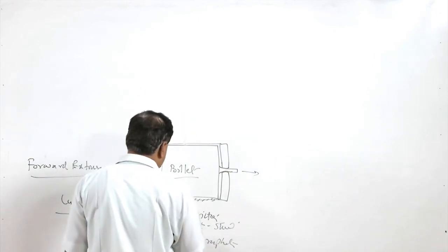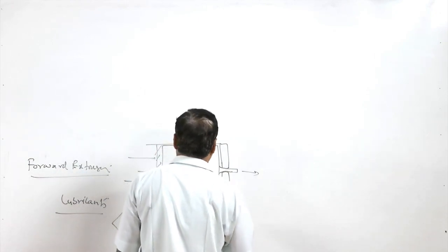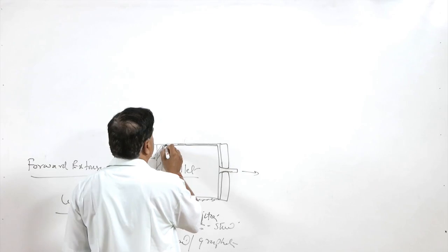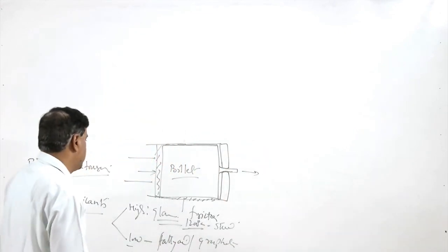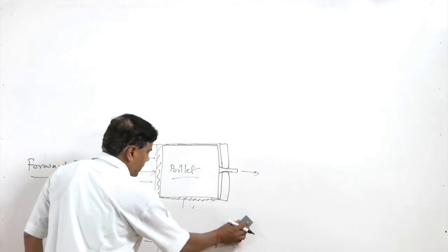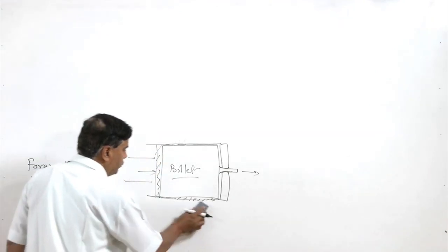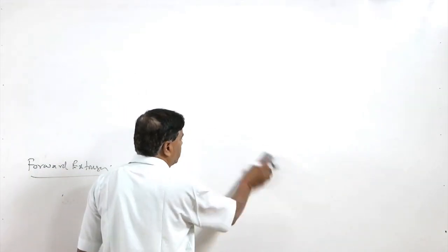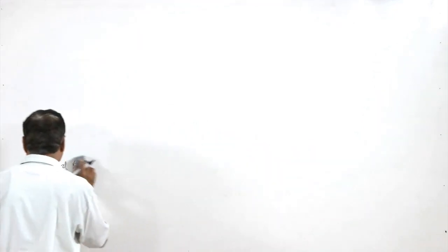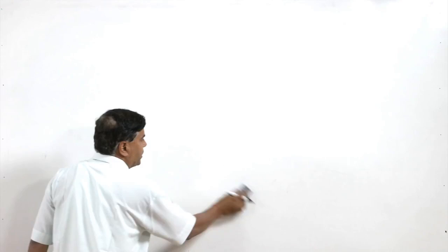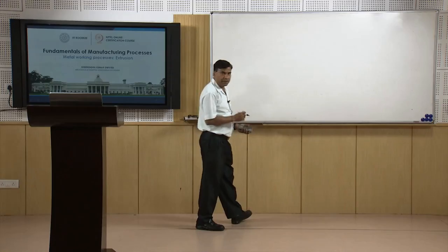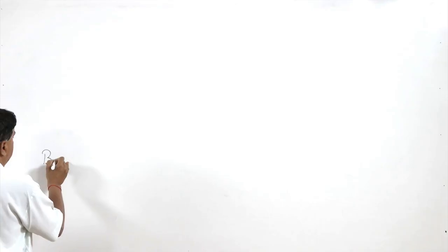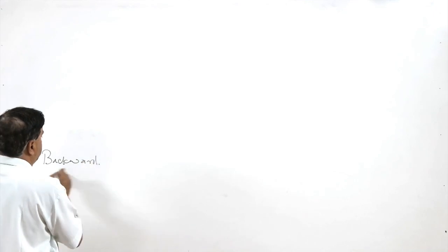The glass melts under the high temperature conditions, and not only does it reduce friction but it also acts as an insulator. So the loss of heat from the hot billet to the cylindrical wall and others gets reduced, while facilitating the movement of the billet within the cylindrical container. The friction between the billet surface and the metallic cylindrical surface is one of the negative aspects of forward extrusion, and therefore, to counter this, backward extrusion has been developed.